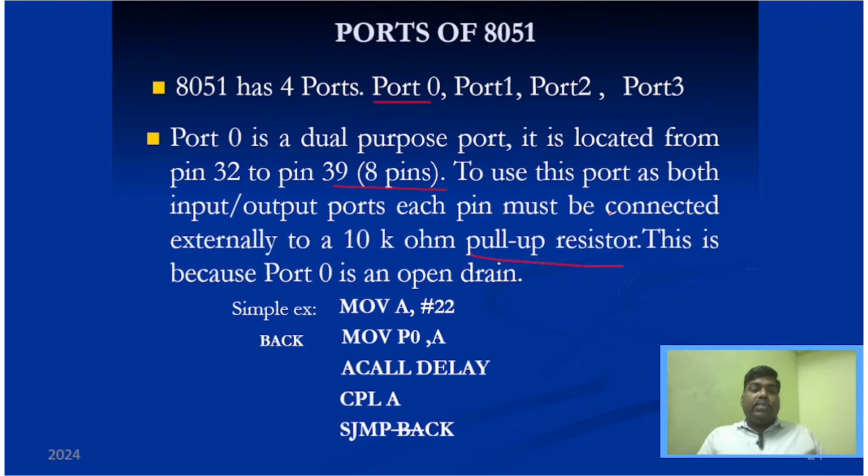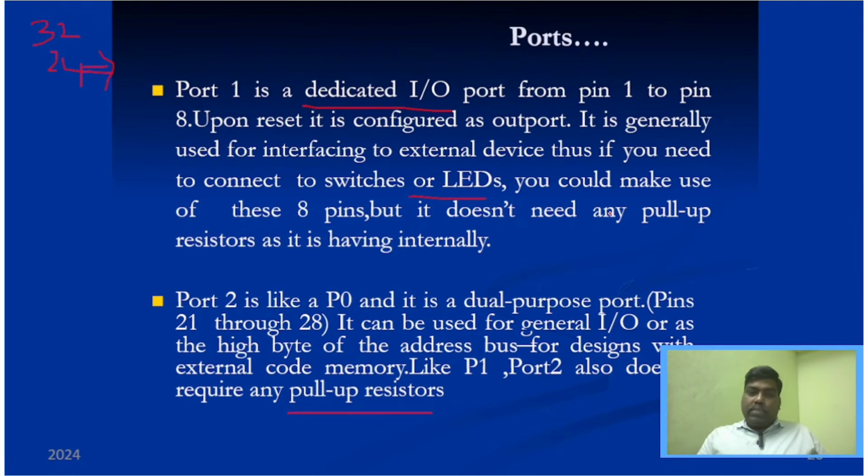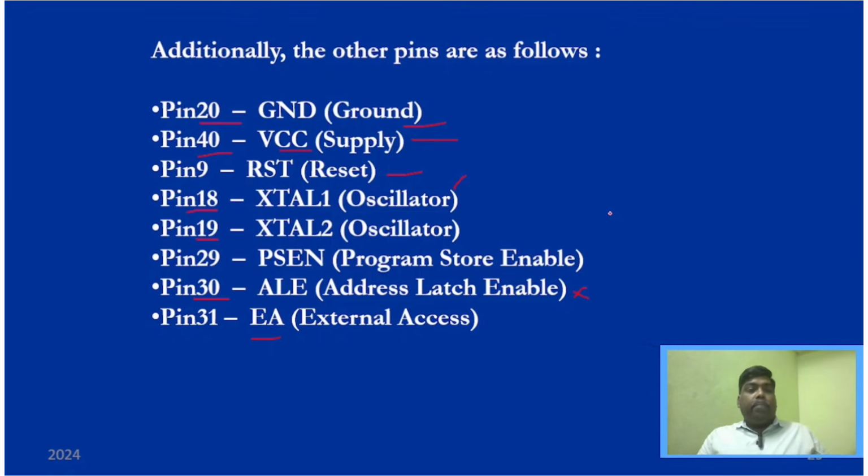So today what we have seen is the port configuration of 8051, and I have explained about the different ports, and we have also seen the use of pull-up resistors and the different pins used in port 3, that is, its different functions, right?